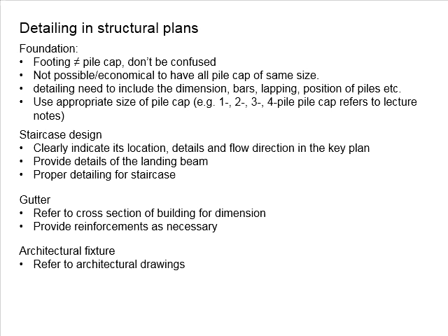Next, you will need to decide whether you want to design the staircase to be cantilever or to be simply supported. Be careful with the reinforcement bar arrangement, as the cantilever staircase will have the reinforcement bar arranged differently than the simply supported staircase. Of course, if you can, try to go for the simply supported staircase. It will be more economical.